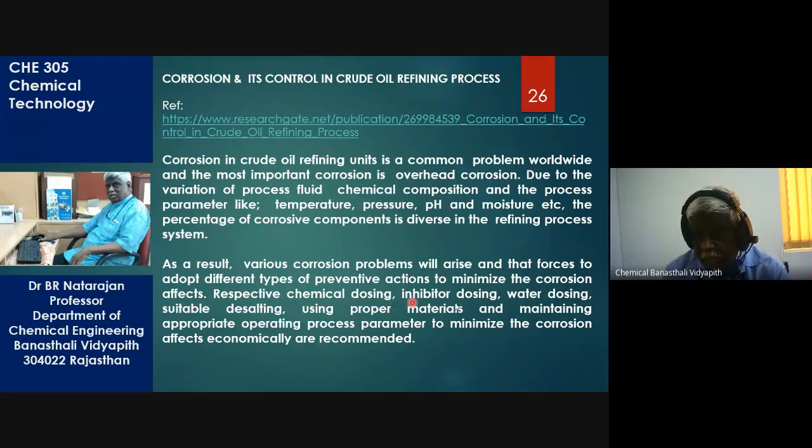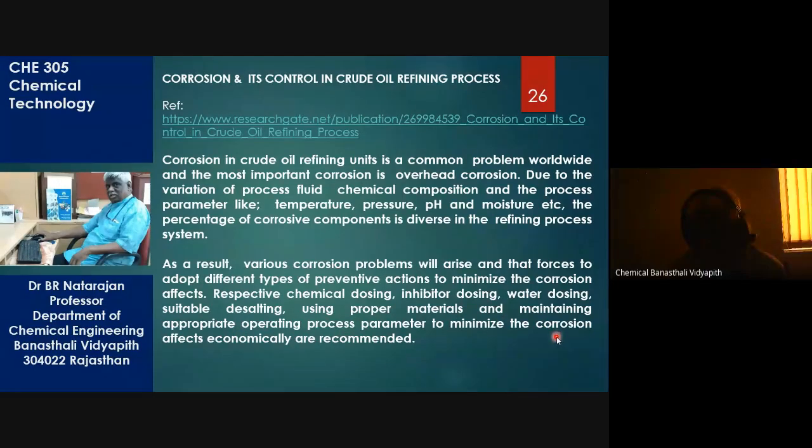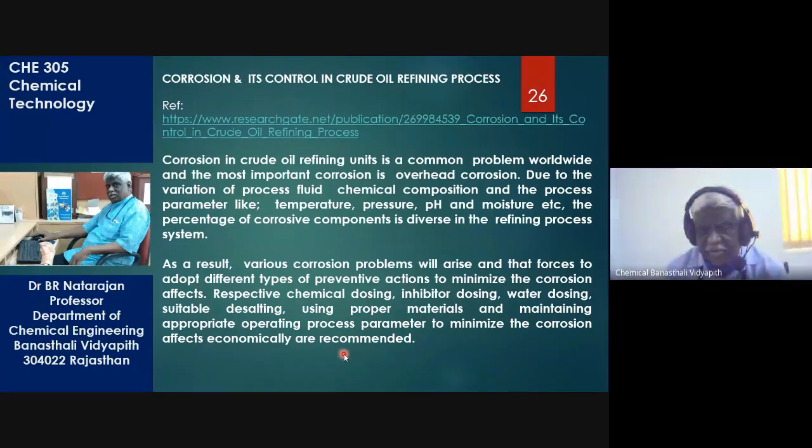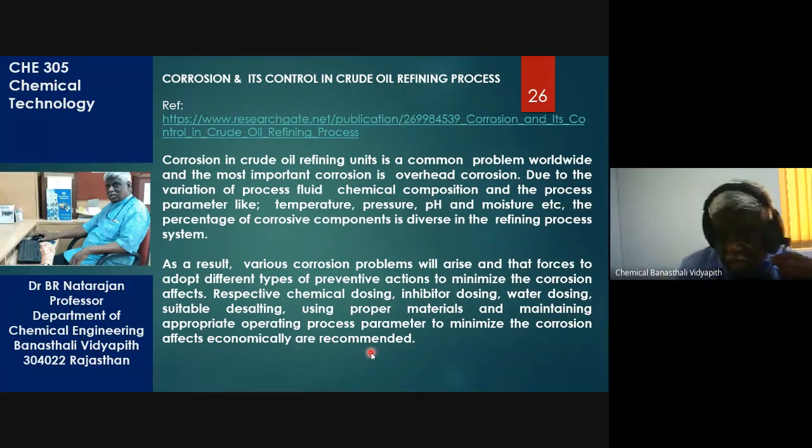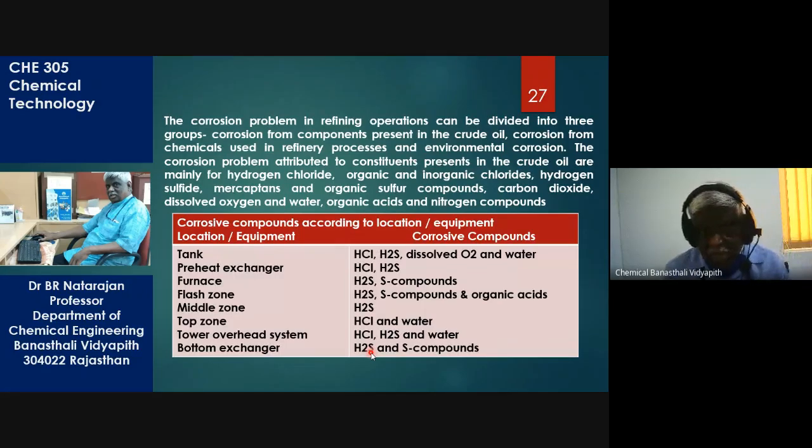There's chemical dosing, inhibitor dosing, water dosing, suitable desalting, using proper materials, and maintaining appropriate operating process parameters to minimize the corrosion effects economically.